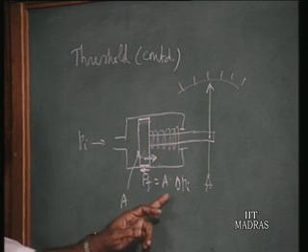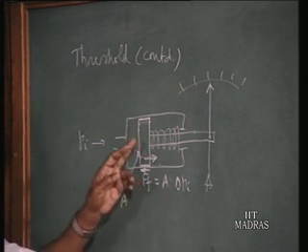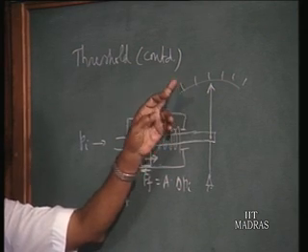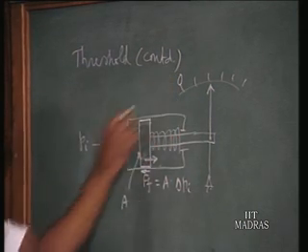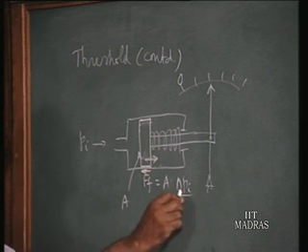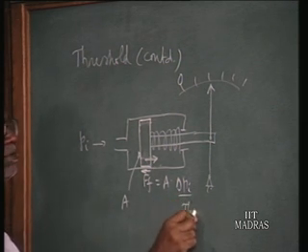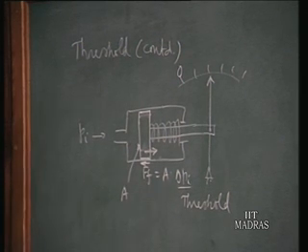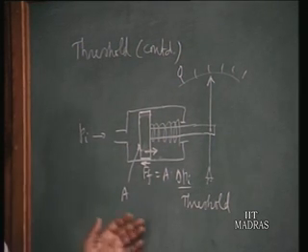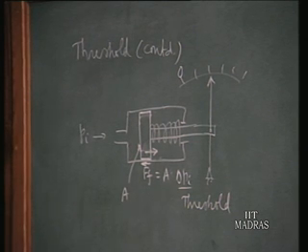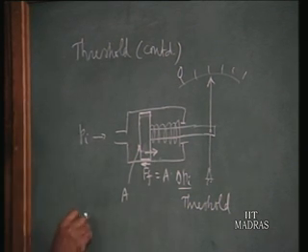Between 0 and delta Pi, there is no movement of the piston, hence no movement of the pointer. So to make the pointer move from 0, we have to increase the pressure from 0 to delta Pi. We call this delta Pi the threshold value. This is the reason why threshold exists in all instruments. Similar reasons are there for other types of instruments. That is threshold. Now the next concept is resolution.